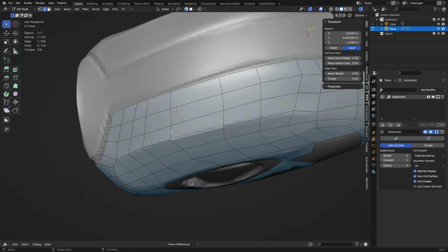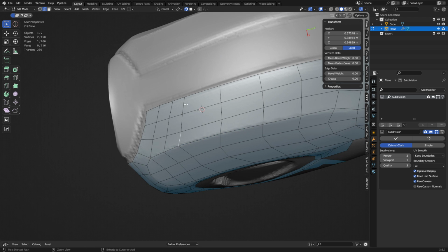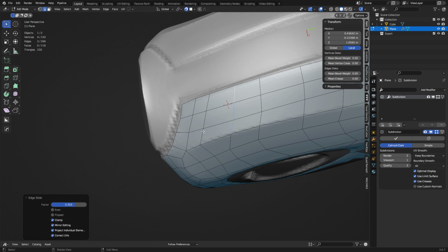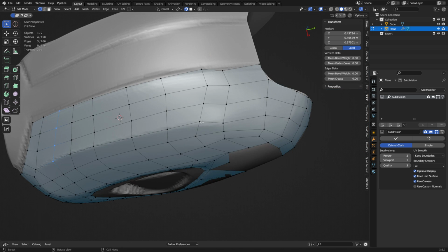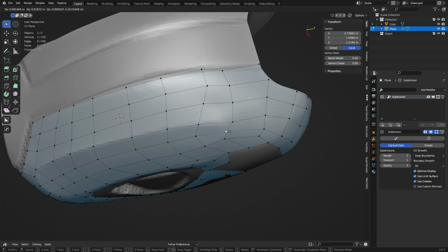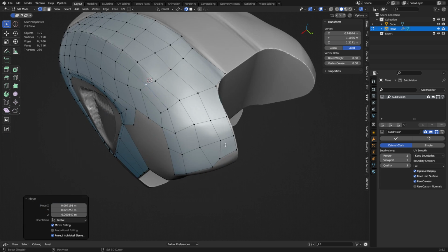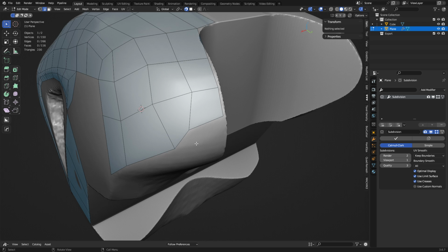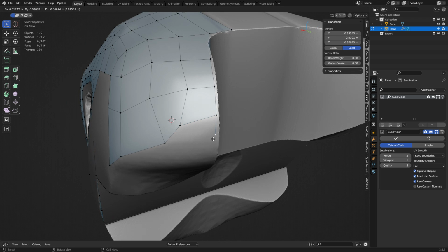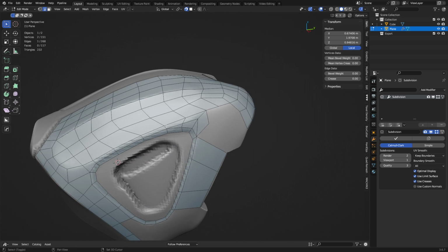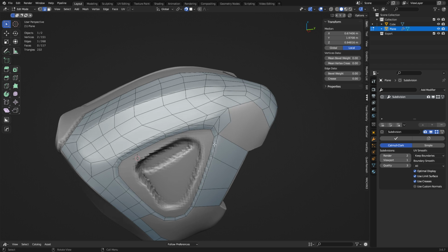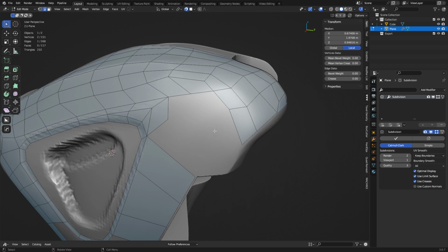So one of the things you want to do is take time to balance things, but learn about reduction methods. I went over this in a few videos. Topology Fundamentals, I think, still had it, but you can do reductions or redirections as well to keep your quad counts kind of manageable in certain areas. Like you can localize densities so that you don't go too dense everywhere, basically.